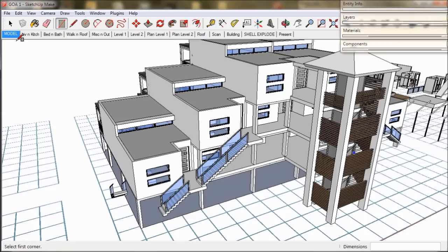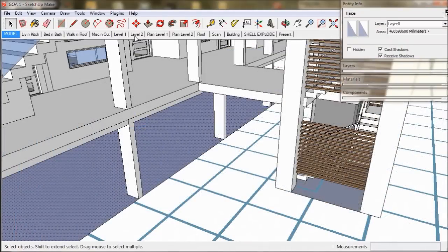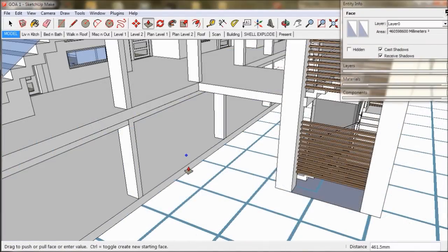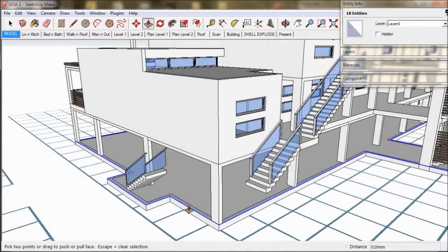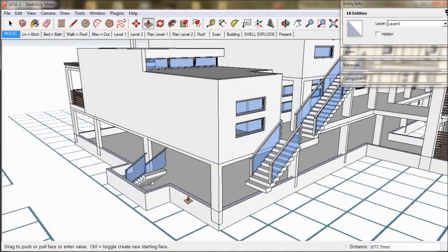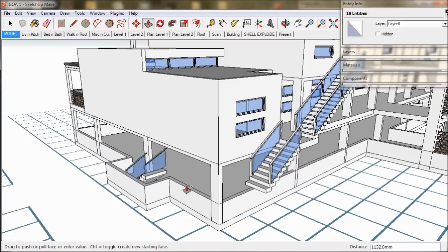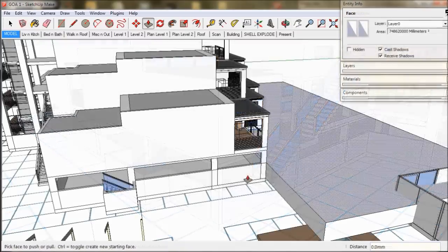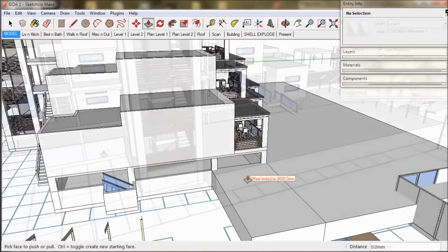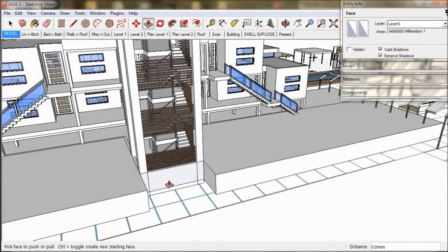So now it's time to finish off the car park retaining walls. Just use the rectangle tool and pull it all into shape. Lift up the retaining wall 1500 or 5 feet. And we form the finished ground level by using push-pull.